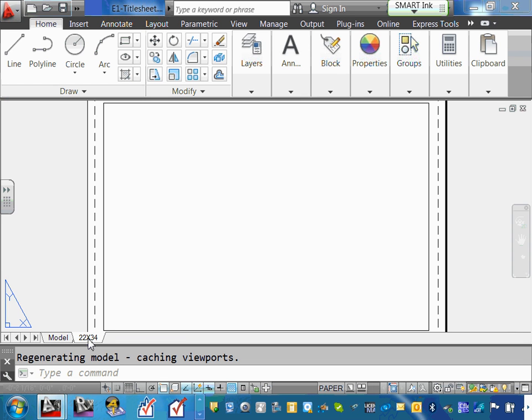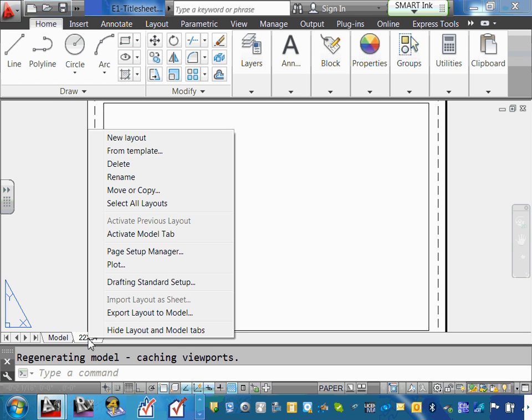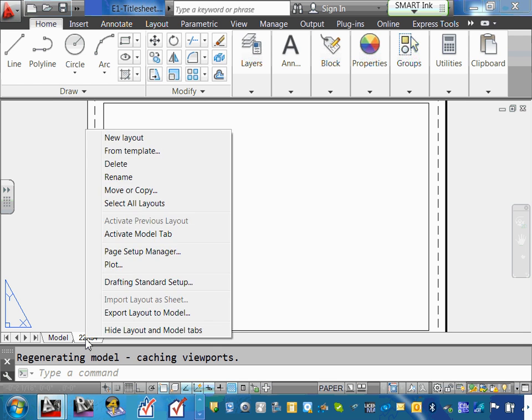Can you guys see? Click on the paper space. Do you see the paper space? All right. Now we're going to go manage. We call this managing the paper, or setting up your viewports and so on. Right click on it, and make sure you're on the page. Right click on it, and where it says Activate, see, it says Page Setup Manager.